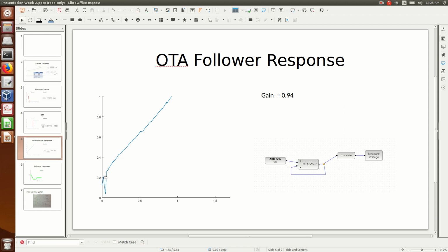Round about ground, the signal gets a bit noisy. This effect round about the ground voltage happens because V plus is increasing relatively fast compared to V minus, so there's a fluctuation which leads to this noisy effect before the feedback loop really kicks in and flattens it out again.